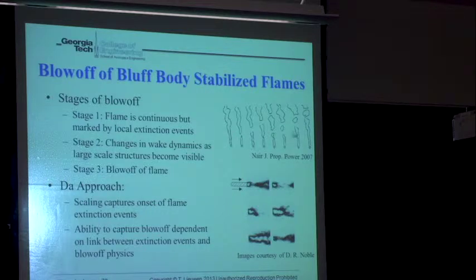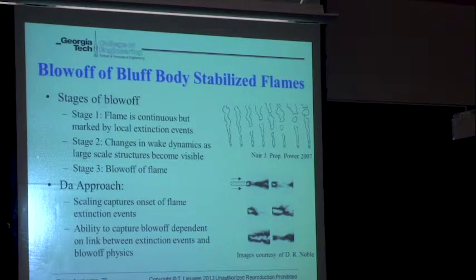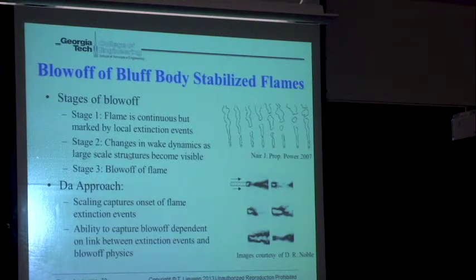Well, as you can probably imagine, if you really start to disrupt what the flow field looks like when the flame is mostly extinguished, and then maybe all of a sudden you go from there to there, bam, the whole flame is back. You can imagine that's creating a whole lot of unsteadiness. And so what we'll see in stage 2 is the whole flow field, the whole flame, just starts to look fundamentally different.